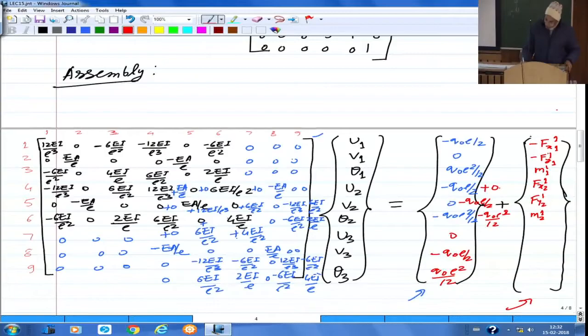And although, if you want, you can transpose into F internal, you will get the relationship between these forces along the global xy directions in terms of local capital X and Y direction. Then when you look at the contribution of the second element, it would be starting again from the 4th row. So here we will have for the now second element first node.